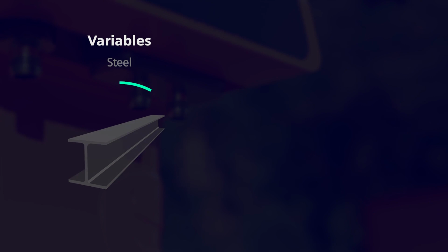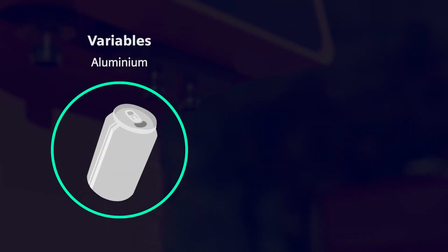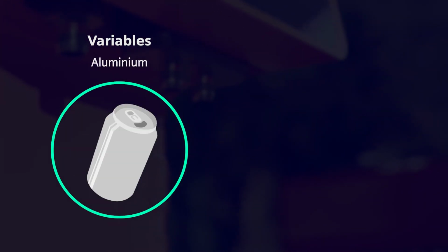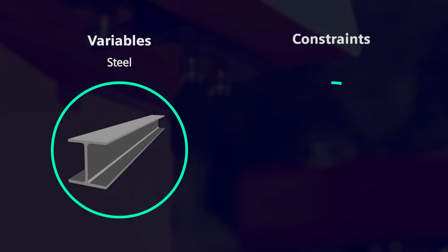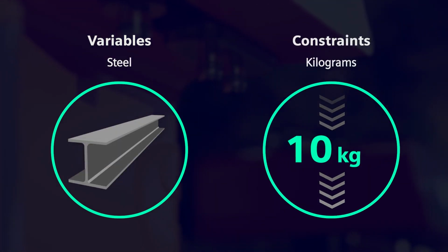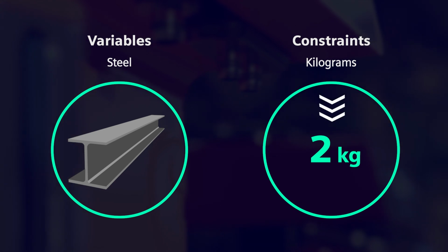At this stage, we've used Performance Predictor to validate material choices and evaluate the mechanical performance of the swinging mechanism. Design Space Explorer will take this one step further and automate optimization processes for multiple design iterations of the tamping system. We'll explore the design space by implementing a range of variables and constraints to create the optimal study. Two key goals here are to find the ideal material to use for manufacturing the part and to minimize its total mass. Let's get started.